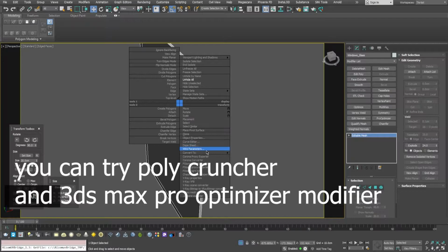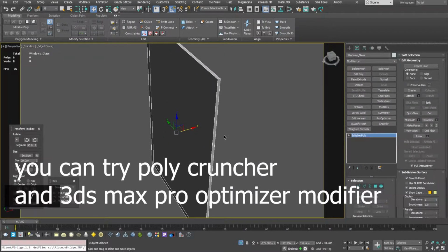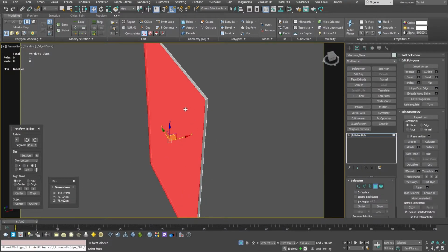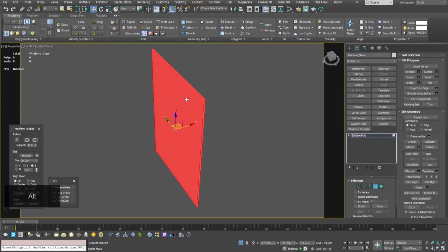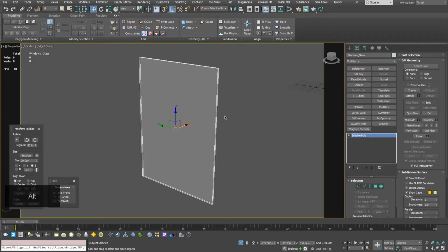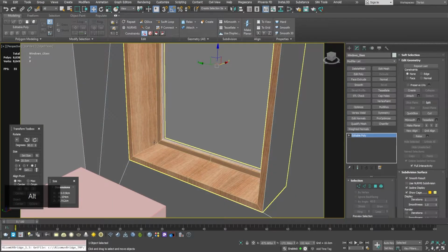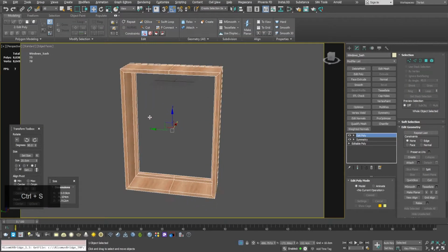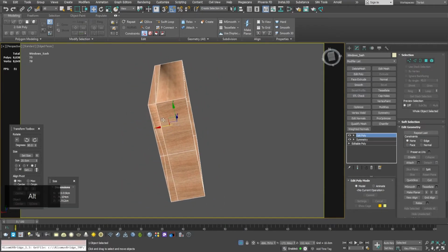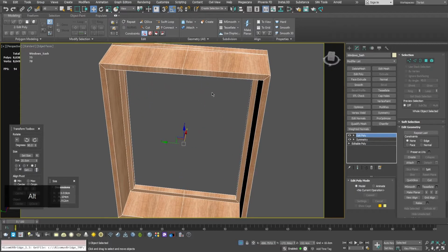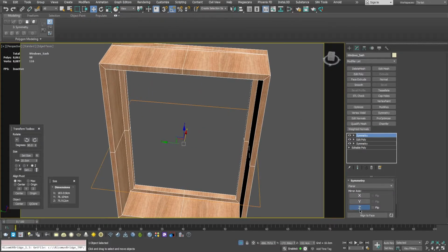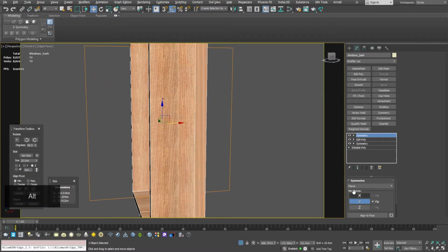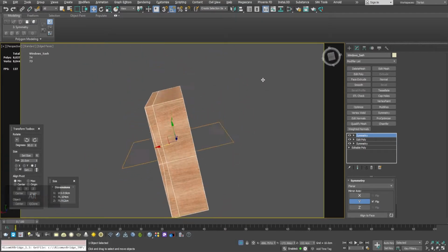So this is, I think, fairly simple as well. Are these six sides? Six, yes. I was just making sure that these were not overlapping double faces. So I'm just going to hit the isolate button, hit Control S, and I think I have to put the symmetry modifier once again and flip it so that this will be correct.